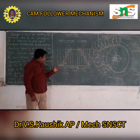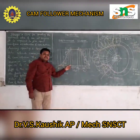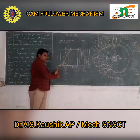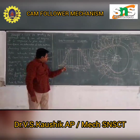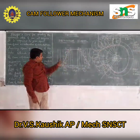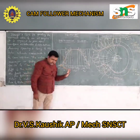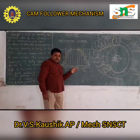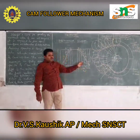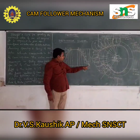Now you should draw the vertical. You should segregate this into 6 divisions. We should mark the points 1, 2, 3, 4, 5 and 6. You should divide this into 6 equal parts and draw the vertical lines. And once again, for the dwell you need not draw anything, and coming to this, once again you should divide into 6 equal parts: 1, 2, 3, 4, 5, 6.